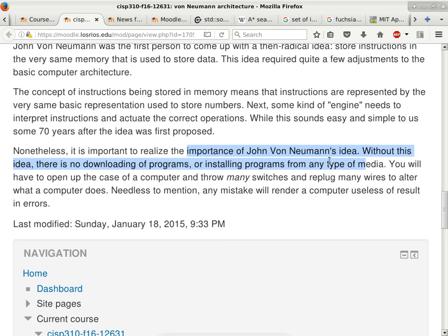The original ROMs can be hardwired, for one thing. It's just the circuit built that way and it cannot be changed. But people quickly found out that sometimes we need to change stuff over time, so it's not convenient if you spend a lot of money to make one chip that cannot be changed. So after a while, people came up with the idea of OTP ROM, one-time programmable ROM.